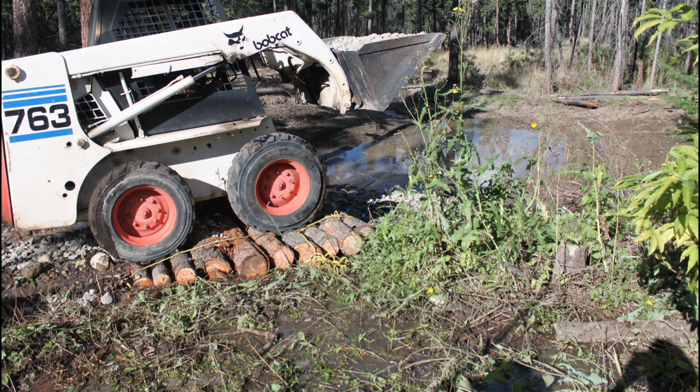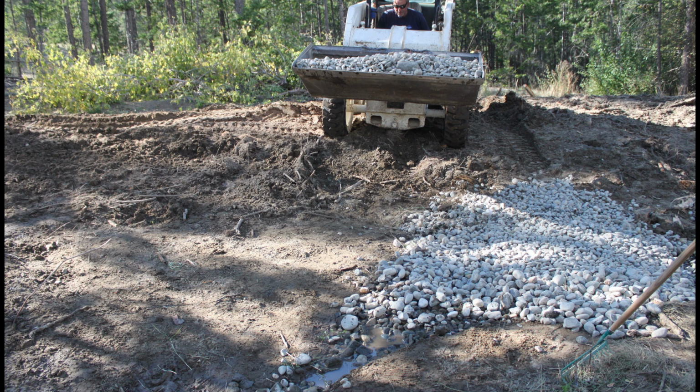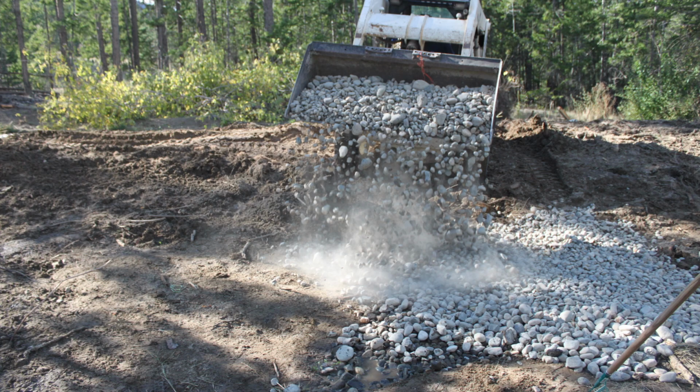We had to cut down small trees and place them in the ground where there was a danger of the bobcat getting stuck. This practice of lining the ground with trees to make a stream crossing is called making a corduroy road. Cliff moves the rock to the spillways that he can access without getting stuck in the bobcat. The bobcat can move the rock faster and for less money compared to using an excavator. This allowed us to keep up with the excavator that was building wetlands.